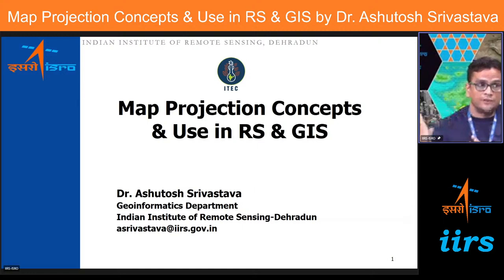The information from 100 years back will definitely be on a paper sheet, and today's may be satellite images. So that map existing 100 years back, you have to digitize it. After digitization, it will be raster data. When you bring that raster data into GIS software, QGIS or ArcGIS, it will not have any projection system or coordinate system.